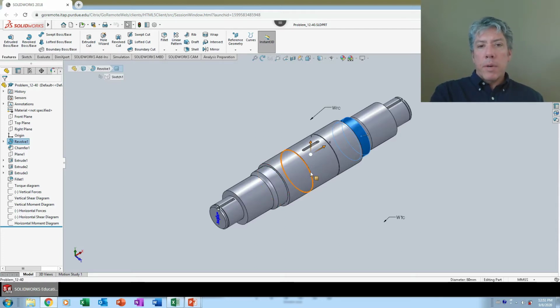You can see several of the features that I've chosen to include. I've got some snap ring grooves on either side of the gear that rides here in the center for power input to the shaft. I've got a snap ring groove down here as well as the key here that will cause stress concentration. And we can talk about which stress concentrator should be the one used at this shoulder for the gear. That's something worth talking about.